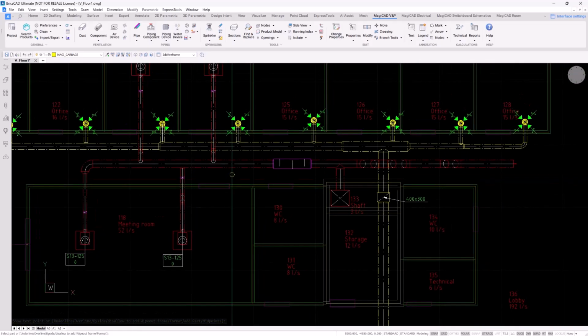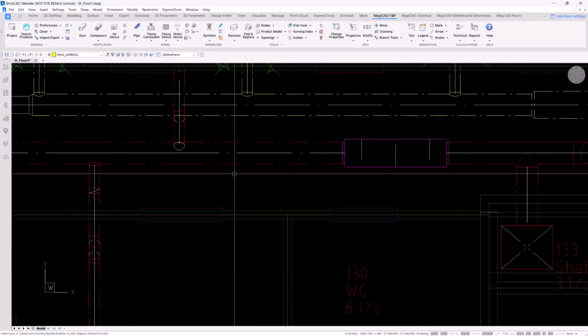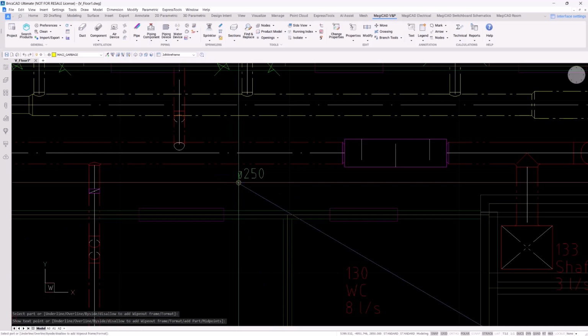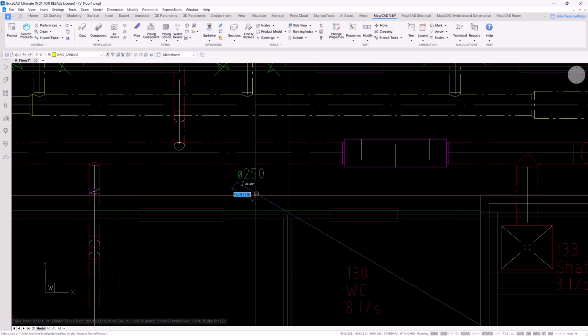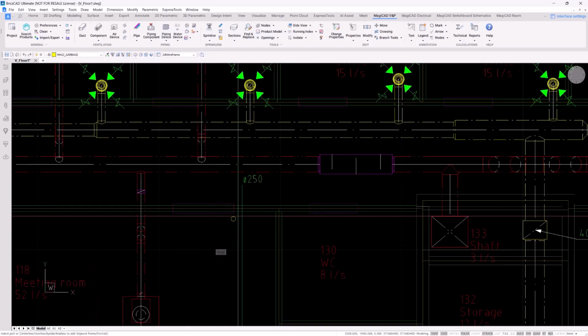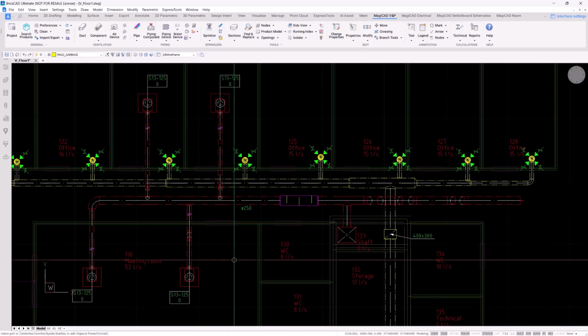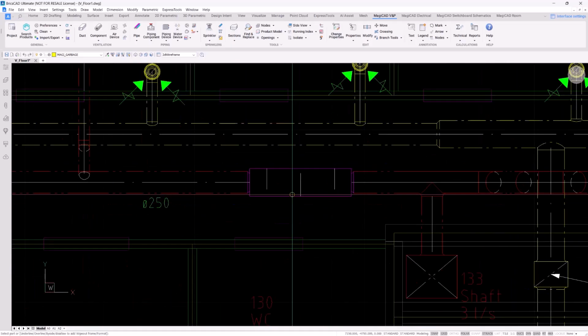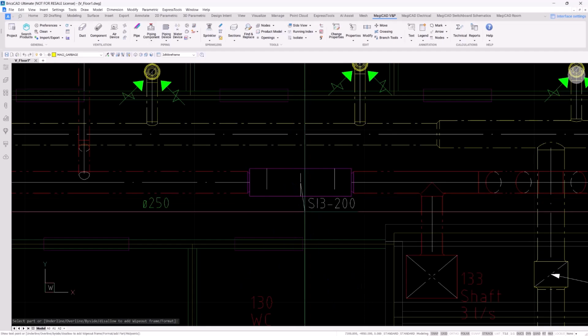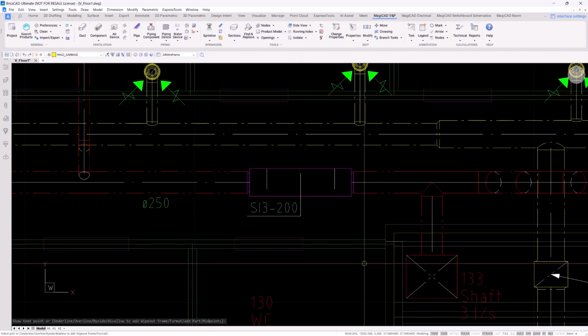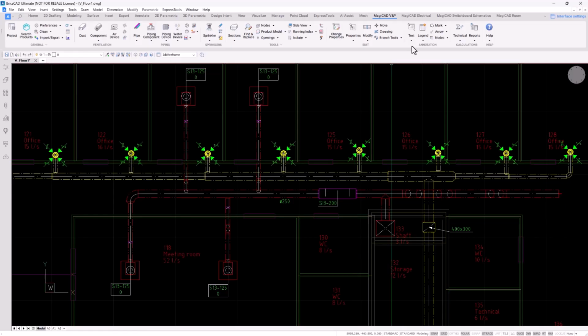In the same way, for ducts, the software recognizes the product class and selects the tag that is active for that. So in this case, it's just a dimension there for duct segments. For components, it seems to be user code and size. So this dimension text tool is for placing the dimension texts one by one.